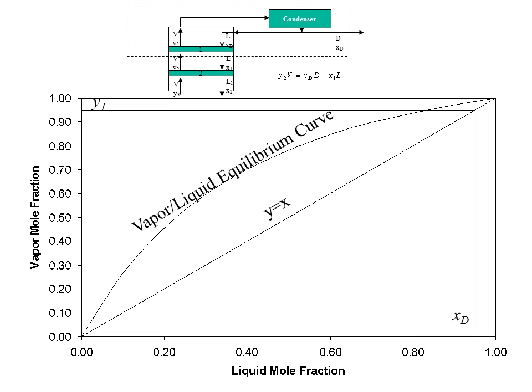Looking at the diagram at the top, we see that Y1 going out of stage 1 goes through a condenser and is condensed to a liquid. It will have the same composition as XD. So we can find that on our y equals x curve, and it is located at about a mole fraction of 0.95.